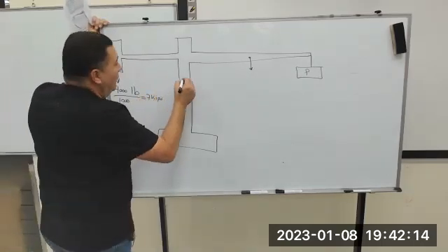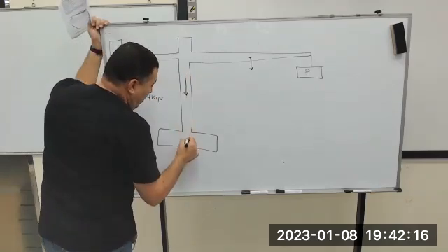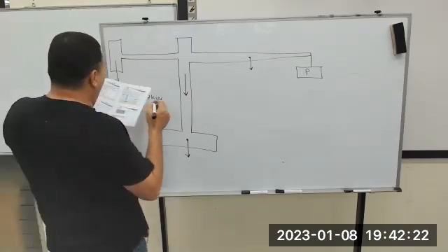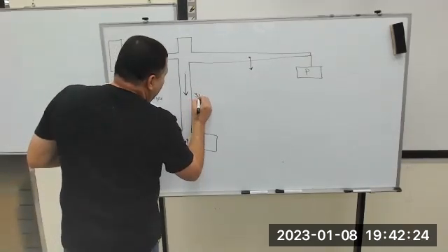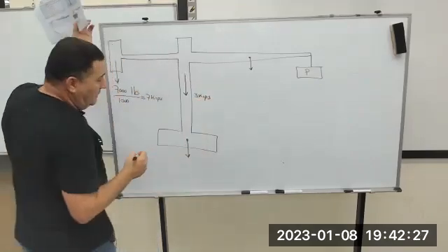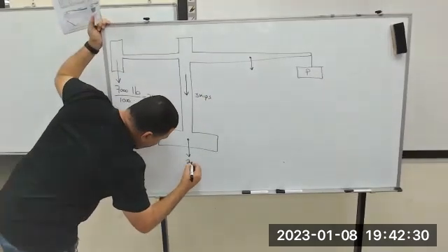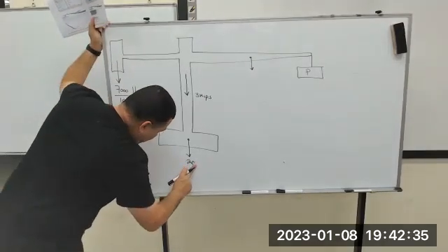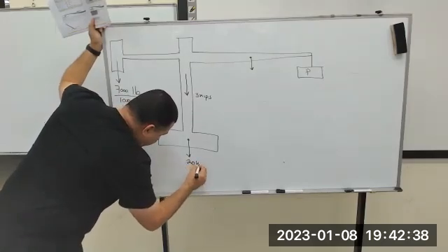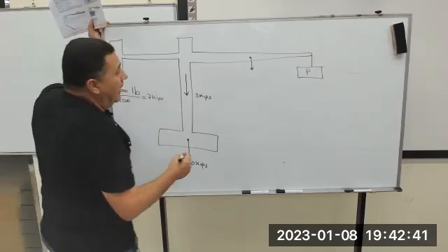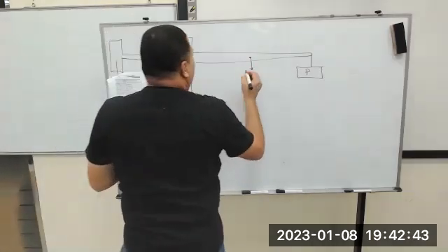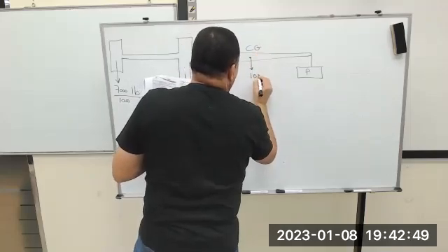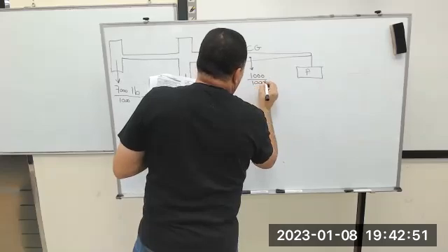Okay, we have the load of the foundation plus the load of the tower itself. The tower itself is 3 kips, meaning 3,000 pounds, and the foundation is 20 kips, meaning 20,000 pounds. And we have a ball of weight coming in at the CG, center of gravity of the ball, equal to 1,000 divided by 1,000, 1 kip.